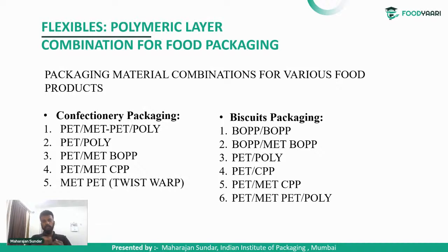Orientation is nothing but lengthening. It will expand so that the wide strands of the polymer get close to each other, which improves the quality of the film. In this case, biaxially oriented, that is, it is oriented in the machine direction and transverse direction. Polypropylene films give great water resistance compared to normal OPP films, unidirectionally oriented polypropylene films.